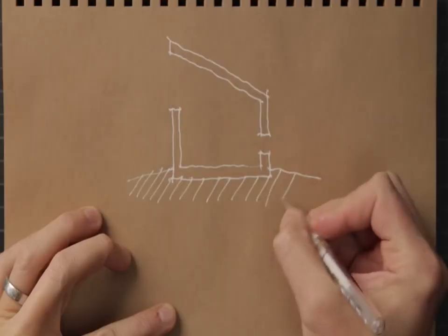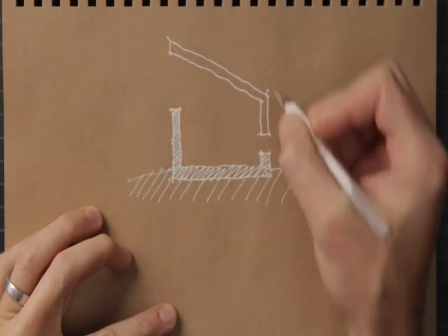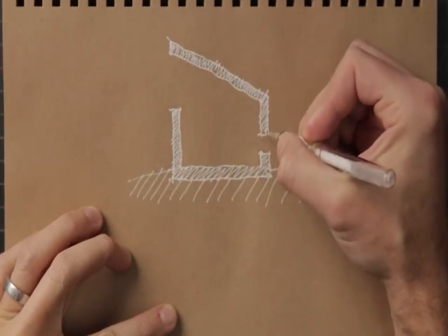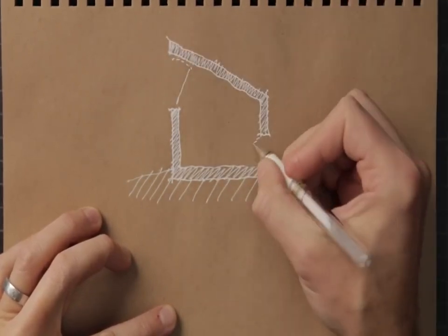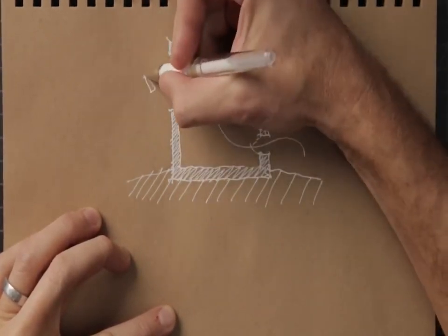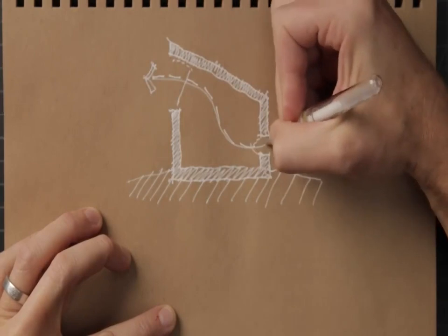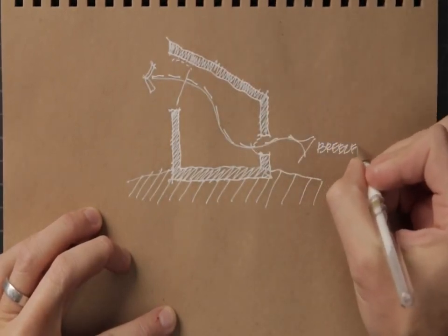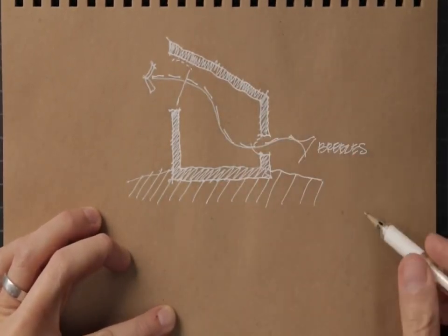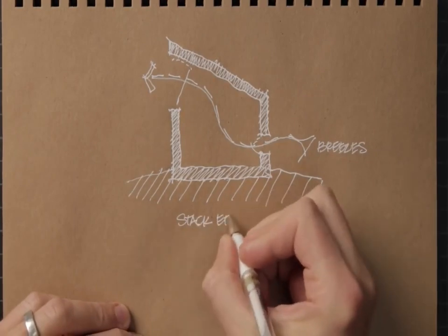Now, the last thing I'll mention about the solar design here is that passively heating spaces this way allows you to take advantage of the stack effect too if you add operable windows up high, as we did in our Claire story. As the interior air heats up and rises, and we open the upper windows, it sets up a natural convective flow, exhausting warmer, stale air up high and admitting cooler, fresh air down low.